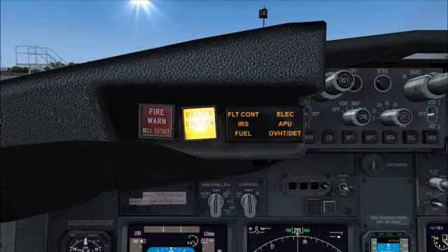Pushing and holding a system annunciator panel causes all of the system annunciator lights to illuminate on both panels. Upon release, the annunciator lights that remain illuminated show systems which have faults. This is called a recall, as it recalls any faults which were extinguished earlier when the master caution light was pushed. The master caution system is archaic by the standards of ICAS, ECAM, and other modern equivalents, but it does the job and can be very effective if used and understood correctly.